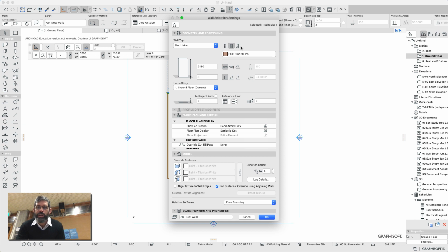Over here, we've also got three different ways of making a wall. This one here is very simple. It's just a wall, like a box. The next one is a composite wall. Very handy if you're drawing up plans for a house, because you can have weatherboards, then building paper, then the timber structure, with insulation in it, then the gib and then the paint, and it does it all in one fell swoop.